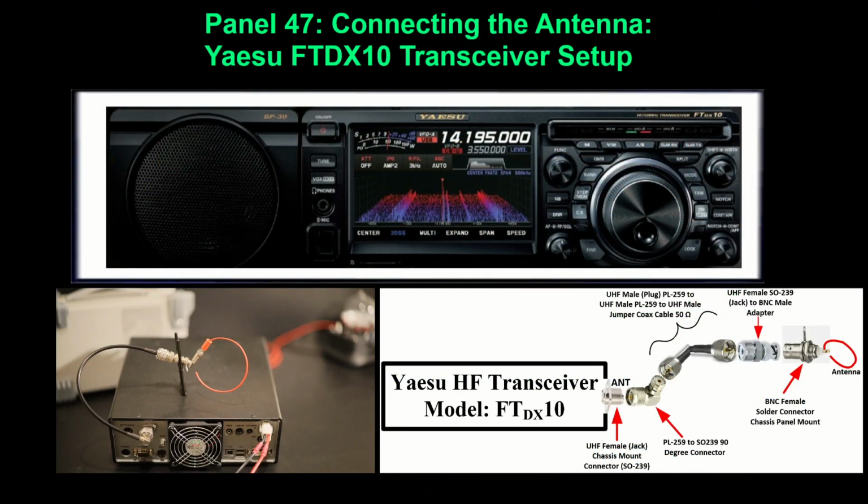The photo features the Yaesu FTDX10 high-frequency transceiver paired with a small insulated wire antenna alongside UHF and BNC connectors. It illustrates how the antenna connects to the transceiver, enabling precise wireless frequency measurements for oscillator analysis while bypassing the protected printed circuit board. To ensure accurate readings without overloading the receiver, I carefully optimized the antenna setup and adjusted receiver functions, allowing controlled signal reception while preserving sensitivity to oscillator frequencies and minimizing interference from background signals.